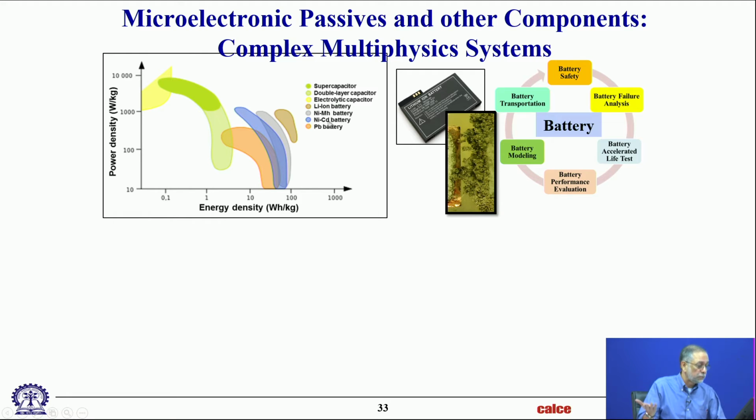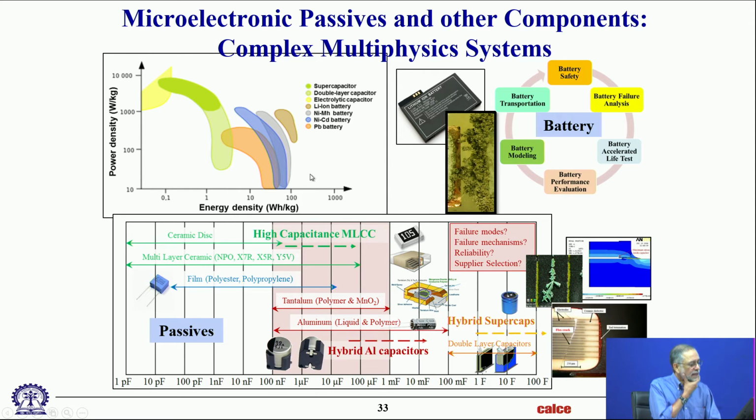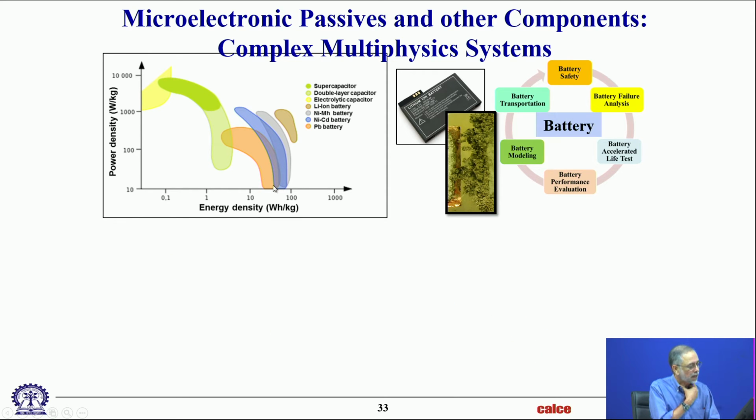Before lithium-ion, we used to have the NiCad batteries, nickel cadmium, or the nickel metal hydride batteries. Those didn't have quite as good a performance as we get out of lithium-ion. You can see where the lithium-ion is, right out here, the outermost tip of the energy density and the power density curves. And that's the problem, of course. If you make ones with extremely high energy density, you can't get a good power density out of it. And if you make ones with extremely high power density, you cannot get good energy densities out of it. The ideal is to stay on that diagonal line, and lithium-ion batteries get pretty close to that.